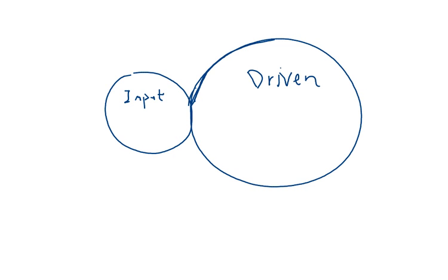So what that means is when your input gear turns by a certain angle, your driven gear must turn by the same amount of linear distance, not by the same angle, because your gears are in contact the whole time. They must be in contact over the same distance, if you will. What I mean by distance, in the case of gears, is arc length. Okay, so the arc length